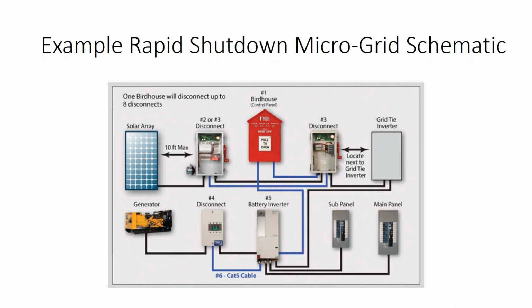Well, if you have a generator backup, generally the generator is located near your point of interconnection. And usually there's a disconnect switch on that generator. So, if you have a house with a backup generator and the fire department shows up, they pull the power to the property and they can quickly identify the generator and that generator disconnect switch and turn the generator off as well.